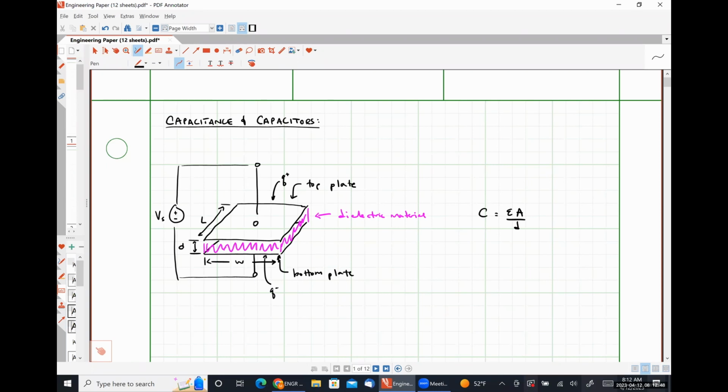So what we are going to observe, particularly when we get into Friday's class, is that it's going to take time in order for us to charge and discharge a capacitor because of how it's harder and harder to add more charge to the system, okay? Now this adding charge to the system thing also actually describes how this device, which literally contains no conducting path, is able to have some amount of current flowing through it, right? Because we would expect that since there's no way to get charge to physically move from the top plate to the bottom plate, it should be impossible to have current.